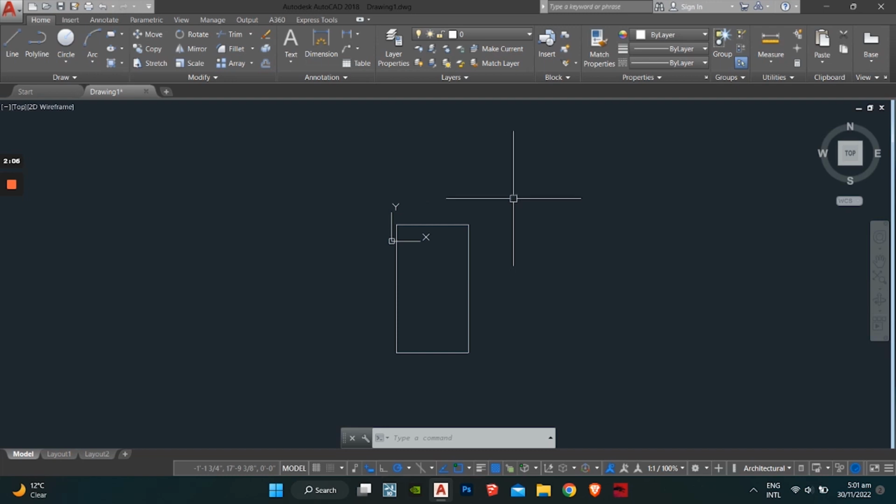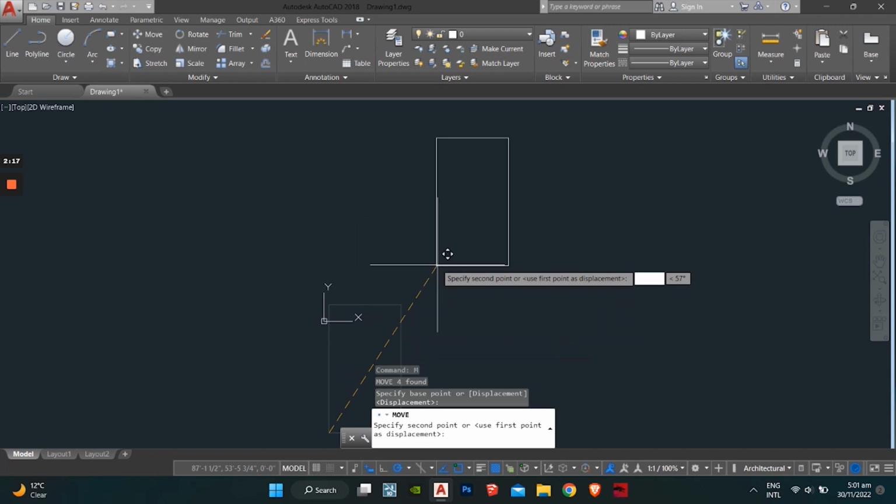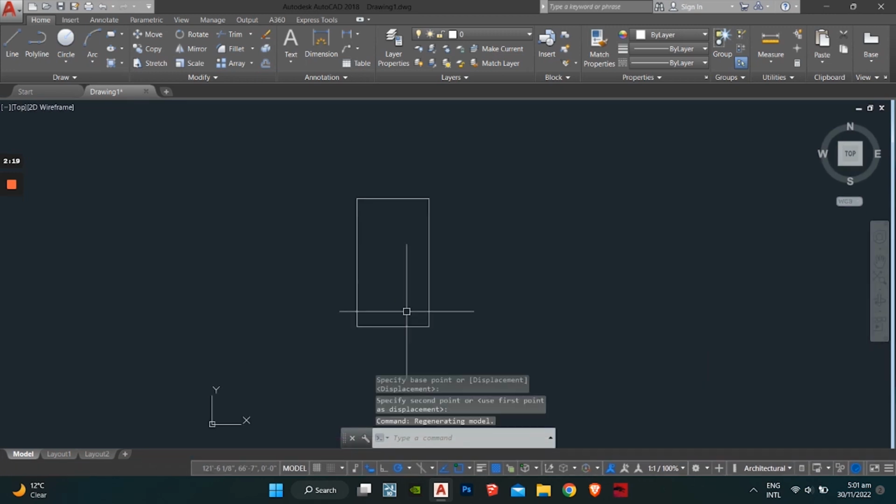This is basically a selected part of the land where you can draft your plan in, a construction area in other terms. Okay, so I don't like my plan being here, so I'm just going to select it. Press M for move and move it up. Okay, I like it here.